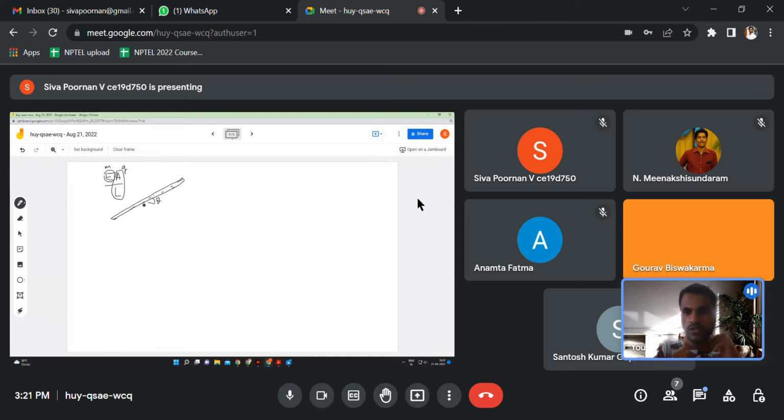So first we need to know what the stiffness matrix does in this context, right? So basically stiffness matrix is relating the displacements to the forces, or rotations to the moments, through a matrix, right? Now what this matrix becoming singular actually means is that I would not be able to find out the moments for given rotations.